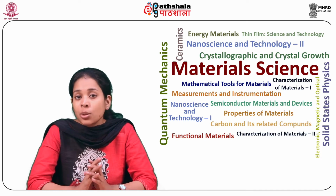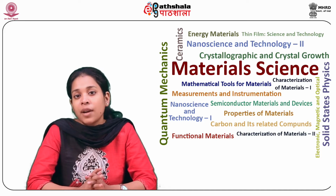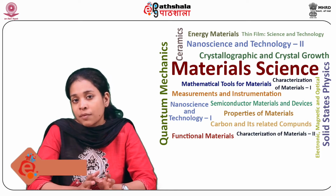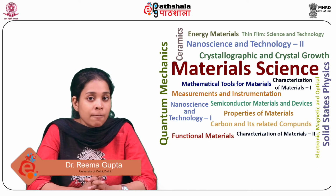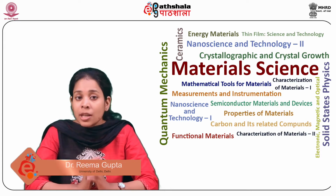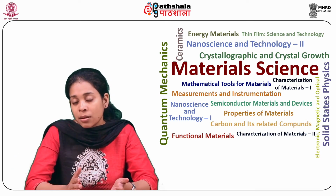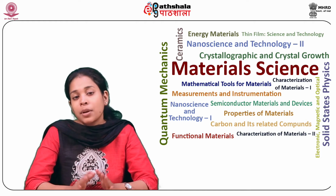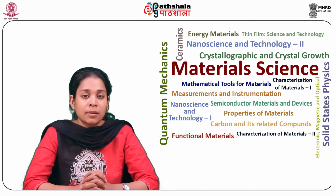And we have concluded that among the three resonators, the coplanar waveguide resonator is the most successful geometry for the transmission of electromagnetic waves in the microwave region from one point to another. In general, the coplanar waveguide consists of a center conductor with two ground planes printed on the same surface of a dielectric slab. Thank you.